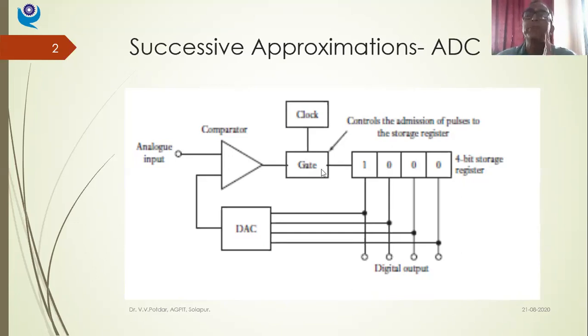Understanding it? I'll repeat it. Just be attentive. I'm not taking any signal from the transducer presently. I'm taking signal only from my clock, whose frequency and whose amplitude I can adjust. So initially I'll generate a voltage pulse corresponding to a frequency which corresponds to a digital or binary number, whose value will be slightly less than the value that I'm going to count.